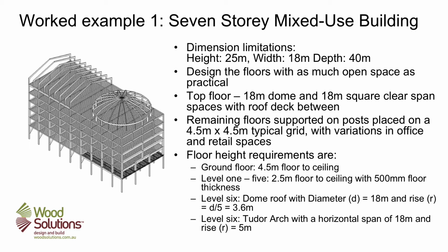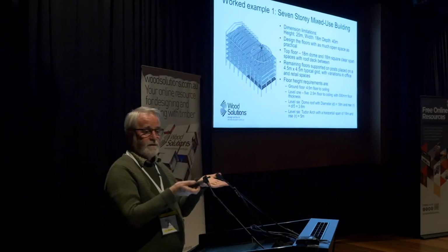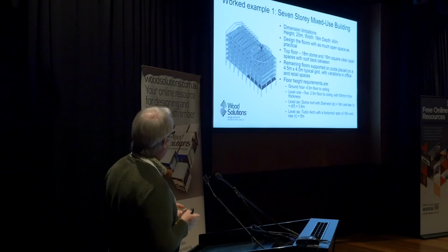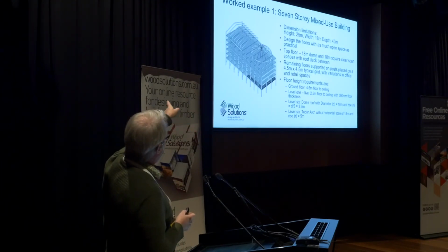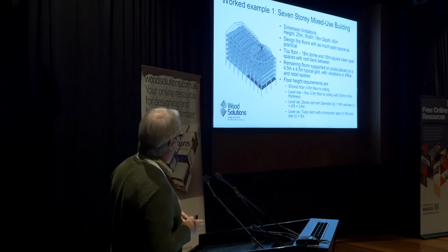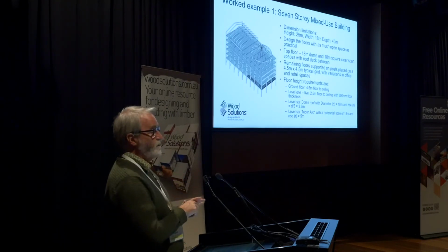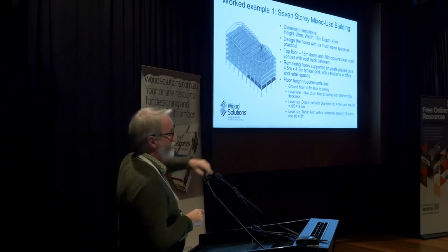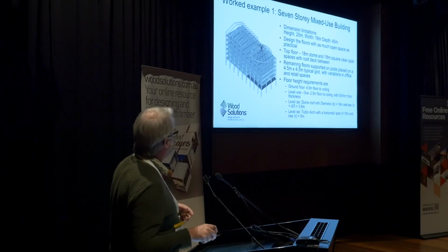With this first option, most of the floors are made of joists, and the joists are all nail plate trusses, and they've then got a fire resisting system underneath them. There's a dome on the top, and there's a portal frame end on the building also. So the grid spacings change. There's a transfer beam in the middle on the ground floor.